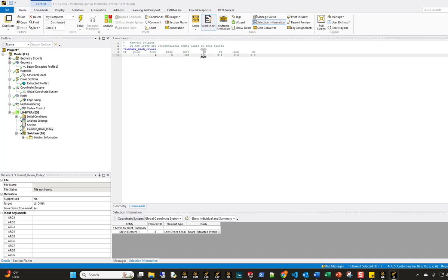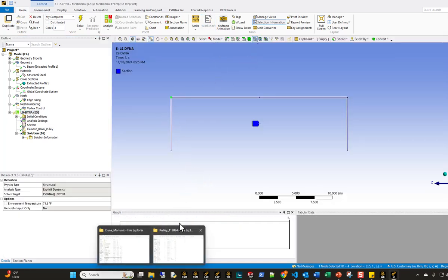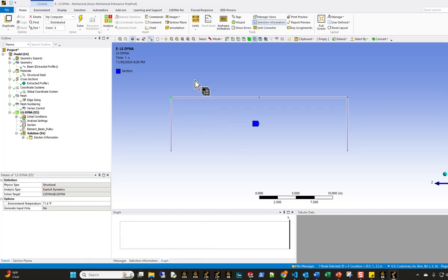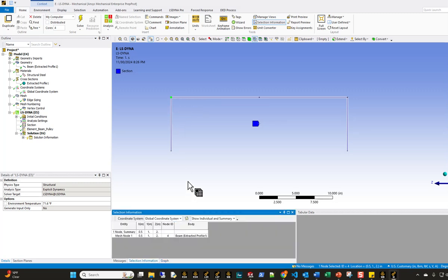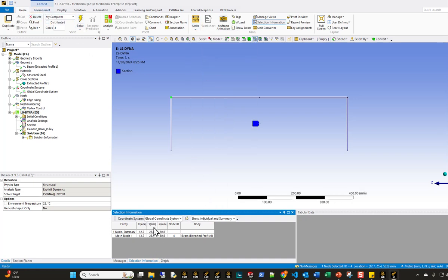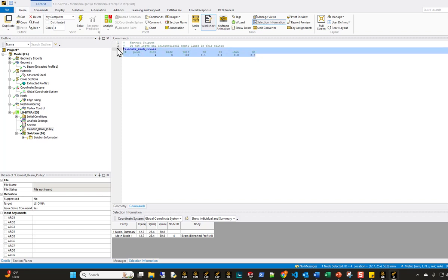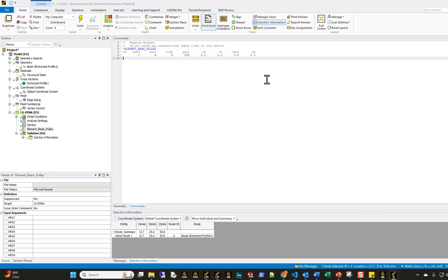Now next, what I want to do is create a node ID. That node ID is not this node. This node right here is not the node ID I'm looking for, because that's the node that's shared by the truss elements. What I want to do is create a node that's in the same geometric location as that one. So the way we do that is to use a node element, but I'm going to change the units to millimeter now, and then put these XYZ locations onto that key card. The way you do that is to use a node ID. Because I have 2 different pulley elements, I'm going to copy this onto the other side, and that's okay.